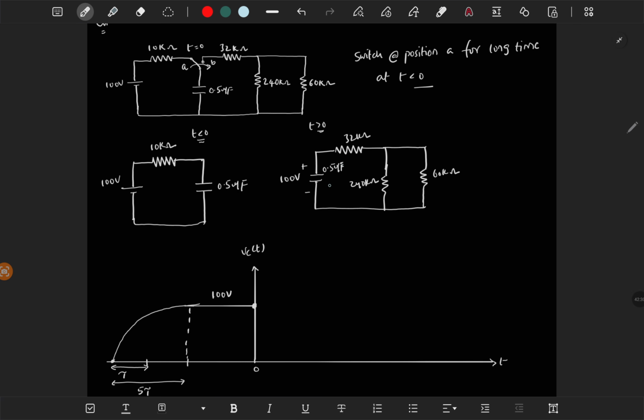Yeah, this is a first order RC circuit without any independent source in the circuit. It means there is no DC voltage source or DC current source in the circuit. So the capacitor will not charge further. It will discharge through the resistor. So if you analyze this circuit, it will discharge completely to 0. We will calculate the time constant later, but this is how it looks. This will completely discharge to 0.